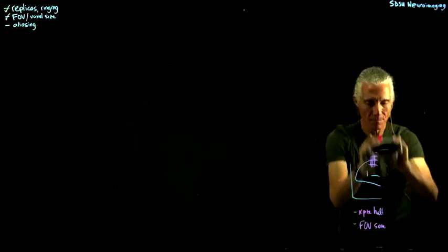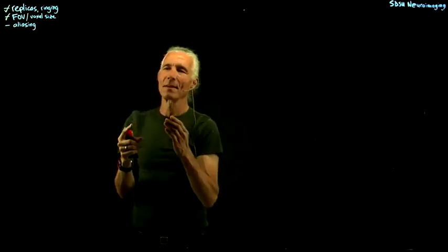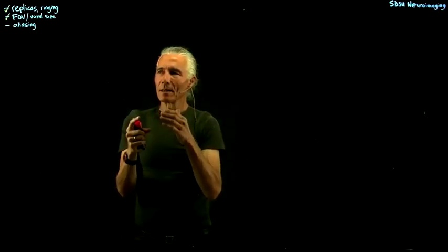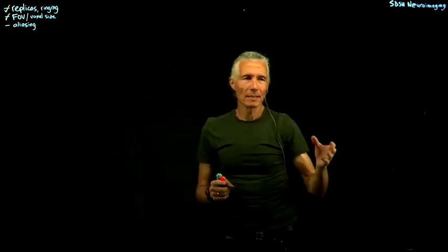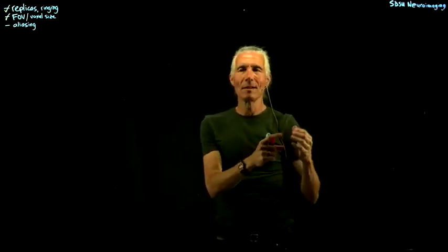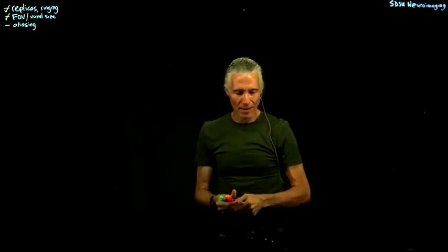An alternate way of thinking of it is, what if we're sampling in time, or in space? And what if we don't sample often enough in space or time? What happens to frequency space? You get wraparound. So it's the opposite of what we were talking about. We were talking about not sampling often enough in frequency space, and getting wraparound in the image, non-frequency space. But the converse is true too.